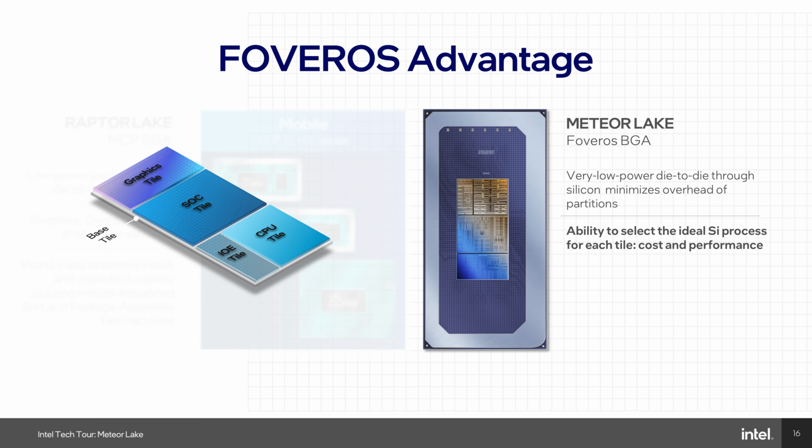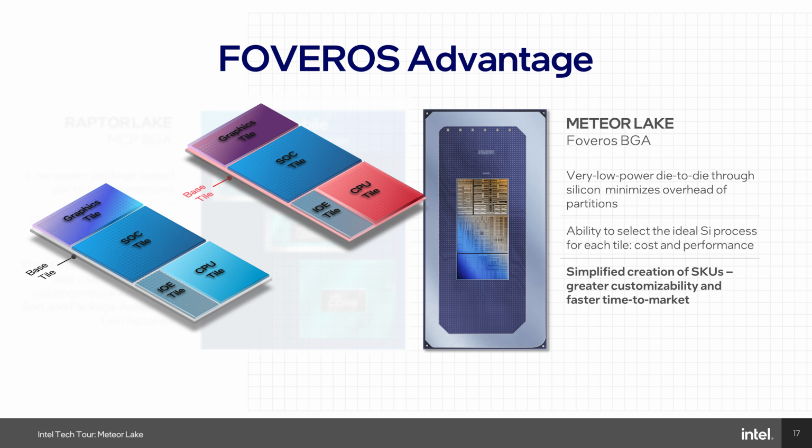So in order to have a reasonable cost for the product, which is always challenging, you need to select where to put the transistor and do the best mix and match between processes, okay? So usually we put where we need the fast transistor on the leading node process. And for example, IOs, which have a fixed frequency, can be used on an N-1 or N-2 process. The second thing is that we look at the architecture scalability. When we build the building blocks, we can define how to build the family by these building blocks.